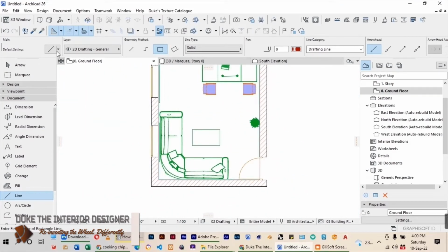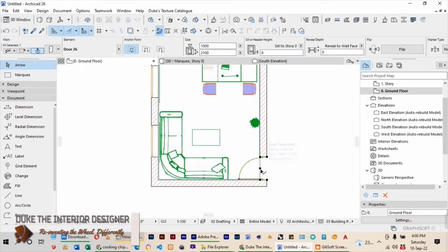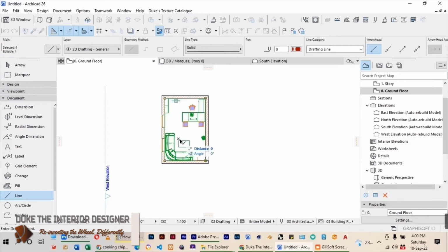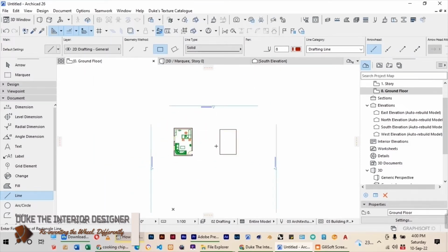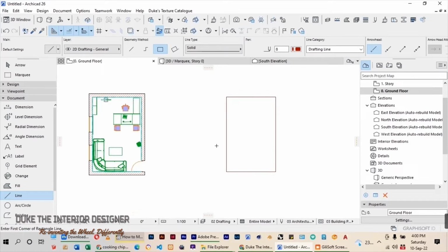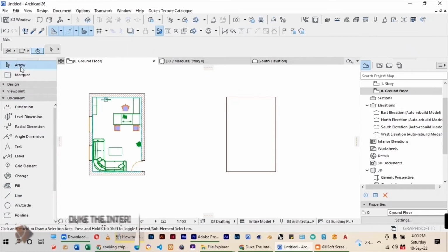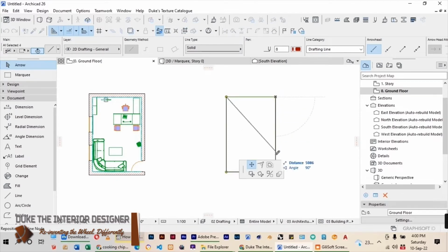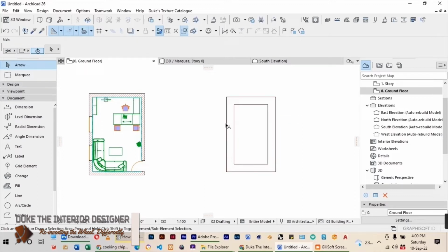That's the office. Pick on your line. You can click on the line, Control A, Control D to move it away from you. I would like to have lights at the side, so normally what I do is to select the lines, make sure that you suspend the group, click on one corner and then offset edges and make sure you control so that you can do an offset of 700. So we'll have lights all around here.